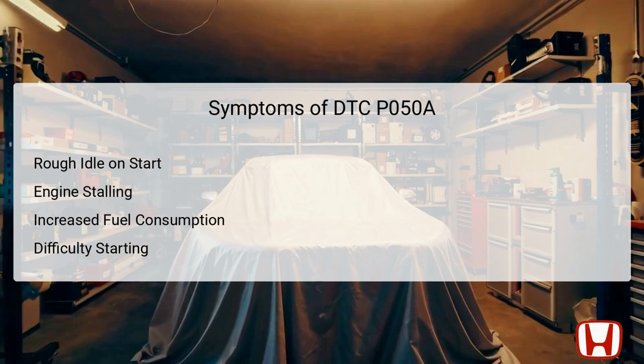Symptoms related to DTC P050A can significantly affect the driving experience. Drivers may notice a rough idle immediately upon starting the vehicle, particularly in cold conditions. Engine stalling can occur if the idle air control system fails to manage the air intake effectively, leading to potential safety hazards.